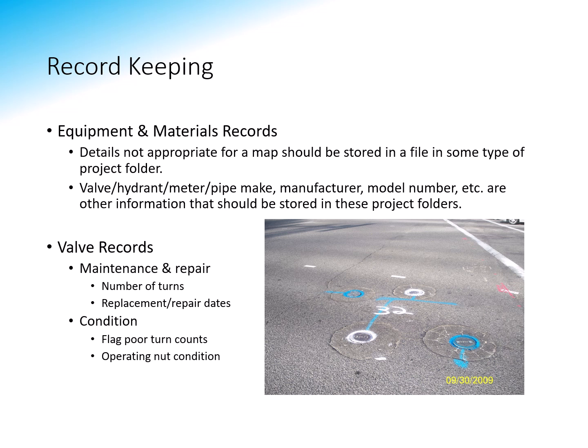Some agencies have a valve crew, most of them should, and they're going out there and turning all the valves that you can see here in this image. They've highlighted what's in there: blow off, air vent, where the valve is. This looks like a sidewinder, but I could be wrong. Anyway, they've called out the number of turns on it, and usually there's a date associated with the last time it was turned. You can flag it with notes to identify that maybe this valve didn't turn the number of turns that it should based on its size, and we need to replace it.